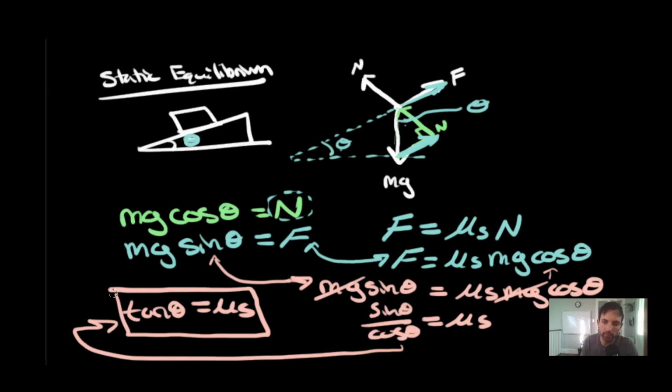And that's kind of how people do it, right? So like if there's an example that we don't know what the static coefficient of friction is between two materials that we're going to experiment with, we can set this little inclined plane up, right? We can put our object on it. We just keep increasing the height of this ramp until it starts to slide. We record how long we end up being and how high we end up being, and then we know the static coefficient of friction between those two materials. All right.